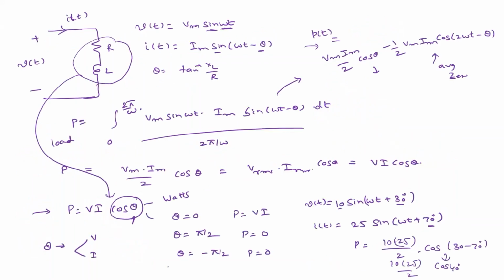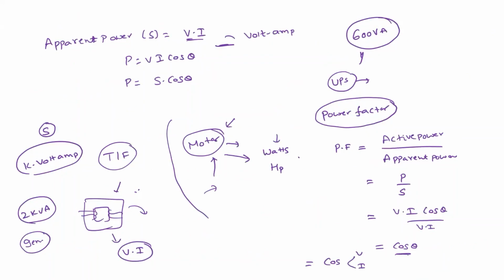So in this particular case, what is the power factor? For minus 40 degrees, it is cos of minus 40, not minus 40 itself. Yes, cos minus 40 degrees, or simply cos 40 degrees. So here, depending on this theta being positive or negative, what kind of load is it? When theta is positive, it is a capacitive load. In case of negative, it is for inductive loads.